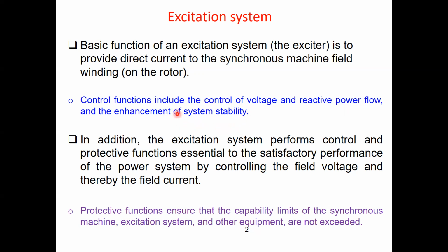And then last time we discussed about that the excitation system with the use of PSS, power system stabilizer, can also be meant to improve the stability of the system, and thus it is the excitation system which provides a source towards system stability improvement, that is to the stabilizer, power system stabilizer, because the power system stabilizer feeds an external signal to the AVR section of the excitation system, and thus that's why here it is said that the excitation system can also improve the system stability here.